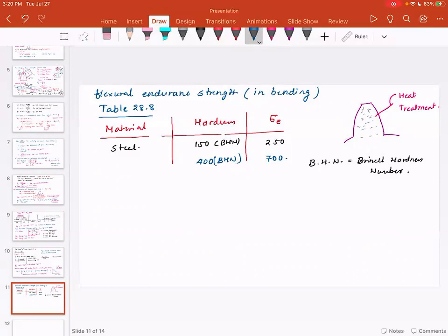And using that endurance strength, we determine static strength. Ws is equal to sigma E multiplied by B multiplied by pi multiplied by M multiplied by Y. Now, at this point, we need to make sure that Ws, static strength, is greater than or equal to Wd.